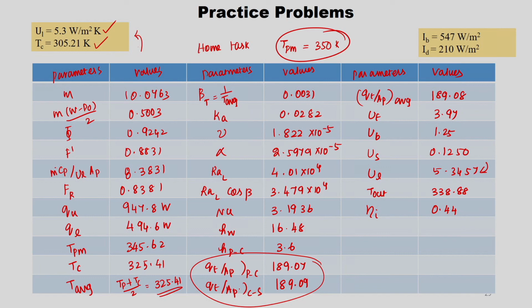But the reason we are supposed to balance this exactly here is that is where we apply certain thermodynamics laws, right. For example, the heat loss from plate to cover should be higher than cover to surroundings, right. So, you should have a higher temperature in the cover and lower temperature in the surroundings, right. If the reverse happens, for example, if your absorber plate temperature is less than the fluid inlet temperature, then instead of gaining heat, the fluid will lose its heat. So, these are all the places you are supposed to apply the thermodynamics laws and check whether you are doing it correctly.